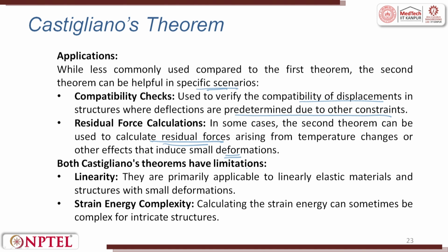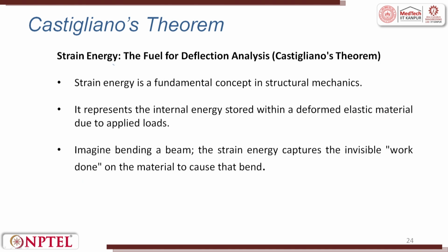Both the theorems have their own limitations. It takes in only linearity and the strain energy complexity. Linearity: they are primarily applicable to linear elastic material and structures with small deflection, right? Large deflection it cannot, like a cantilever swinging it cannot. Strain energy complexity: calculating the strain energy can sometimes be complex for intricate structures. The strain energy, the fuel of deflection analysis.